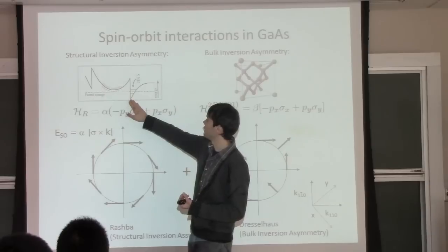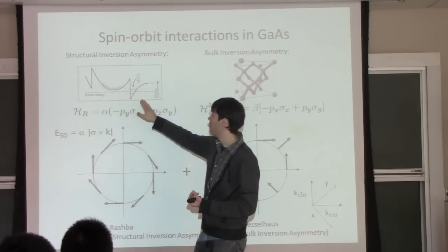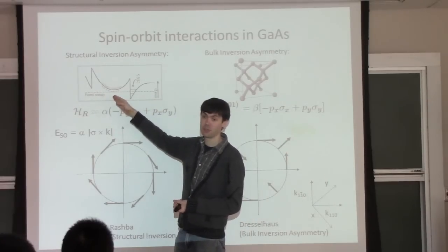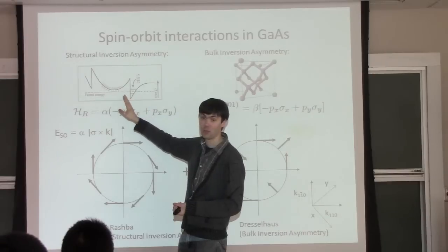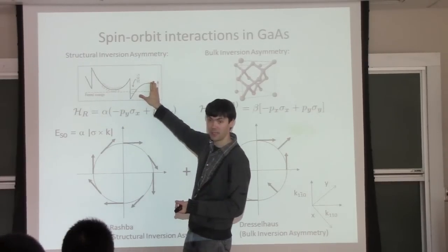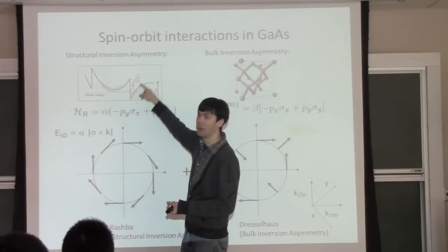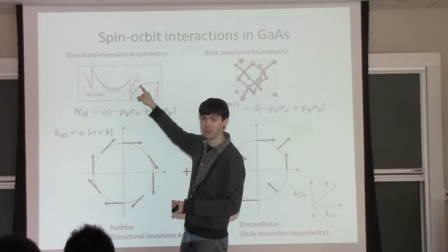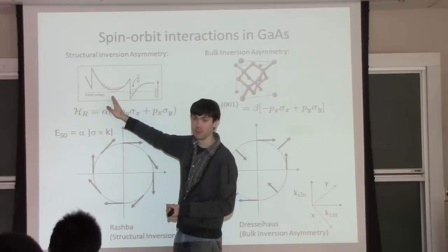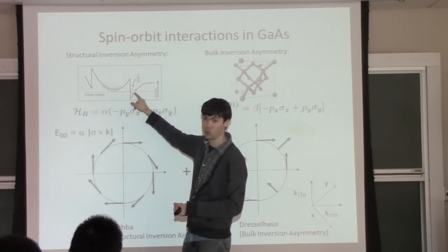So asymmetry like this. Remember, this is the diagram of the band edge of the conduction band for electrons in the gallium arsenide, aluminum gallium arsenide. So this was aluminum gallium arsenide. This was gallium arsenide. And electrons are trapped at this interface in this quantum well, triangular quantum well, between gallium arsenide and aluminum gallium arsenide. And they're created, induced by these positive dopants in this well.